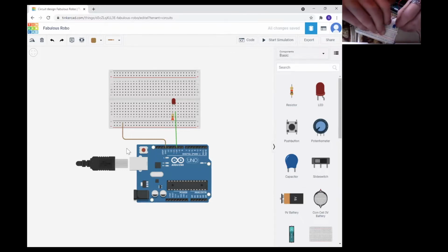So we've got our resistor here, the 220 ohm resistor, which is generally the standard 220 ohm that we use, particularly for LEDs because of the amount of resistance. So if we put one leg, that doesn't matter with these legs because they're exactly the same size, one leg into C1 and the other leg needs to go into, they're a bit fiddly, D2.